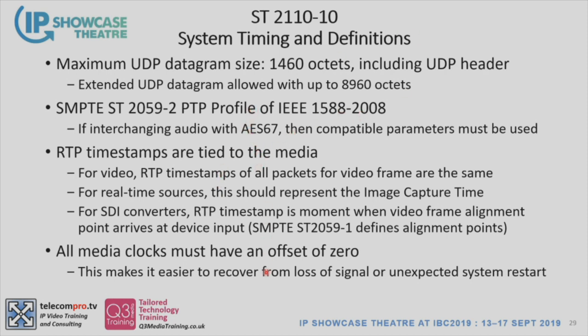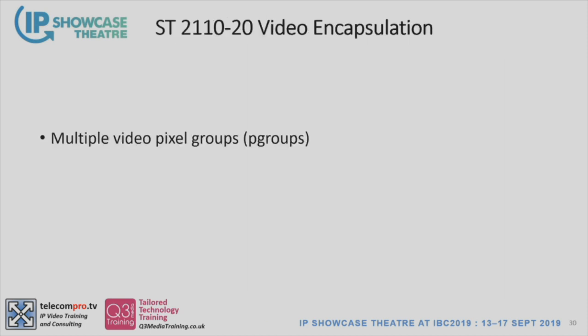And one thing that's definitely specified in 2110-10 that's crucial to interoperability and quick system recovery is having zero media clock offset. And what that basically means is that all the streams in a network all need to use the same reference point for starting their RTP clocks, and it prevents a lot of issues when you have system resets and things like that. Video encapsulation.